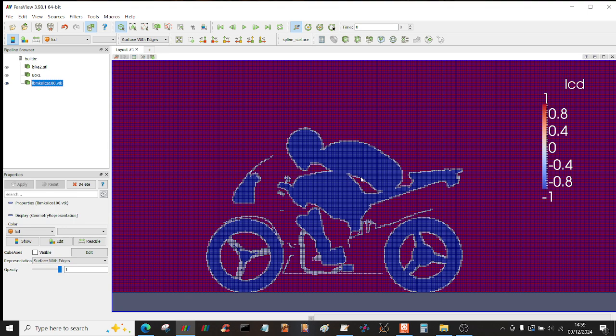For the lattice Boltzmann method, all of the cut cells in the dead region is the obstacle, which means that the flow isn't going to go there, or at least it's supposed to bounce off that region. It's not essential that you have all the dead zones. It doesn't really matter if there's a leak, because the obstacle is still going to be defined by the cut cells.